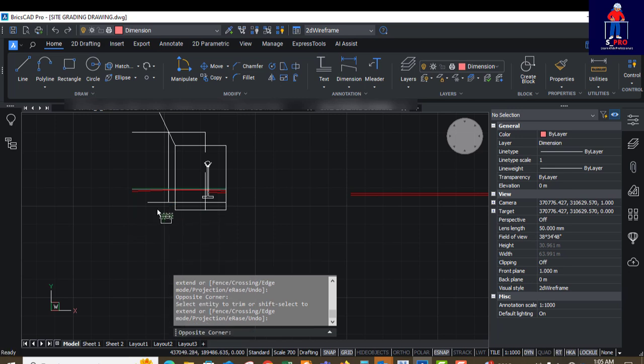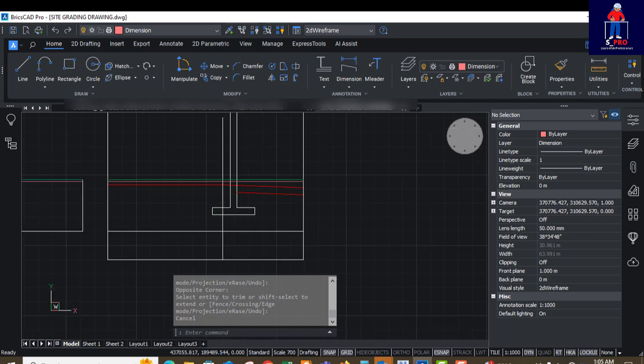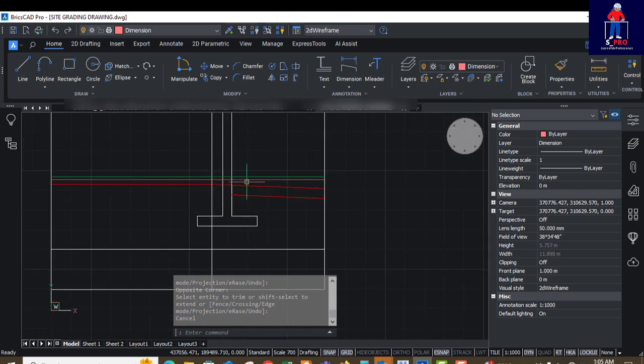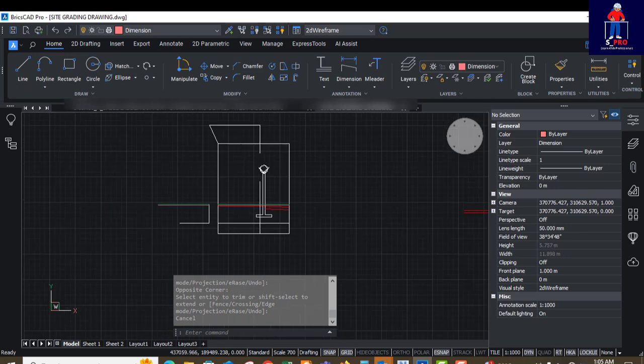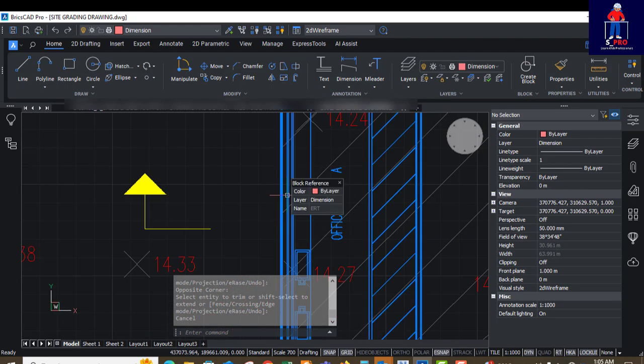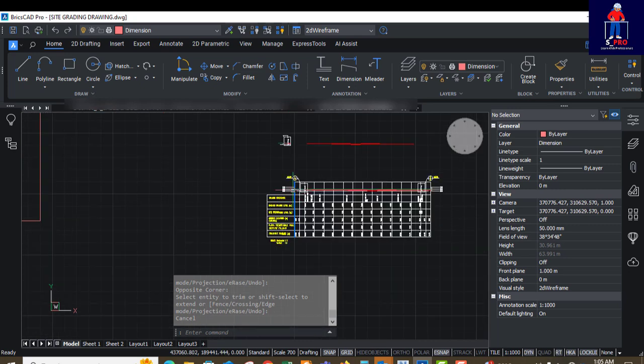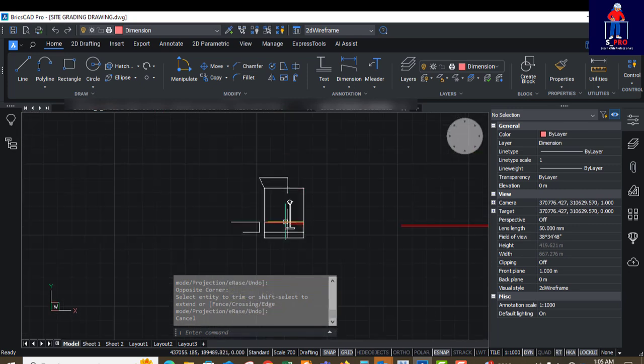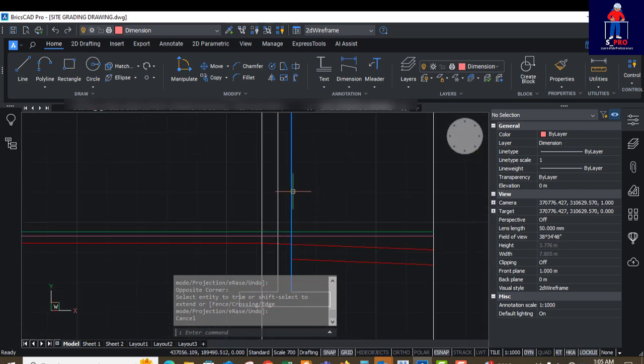Trim off all this. Then from here, this is my fence. You go and check from the plot plan what the distance from the fence to the drain is. The drain, sorry. You now offset that distance. When you have offset the distance, you put your drain to scale.